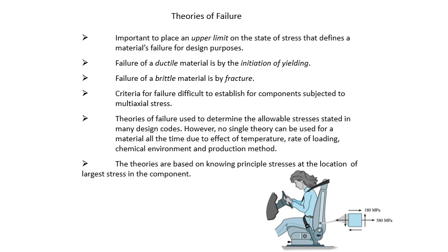Why do we need to know theories of failure? It is important for us to place an upper limit on the state of stress that defines the material's failure for design purposes. So normally we use this theory when we design a new product from scratch, or when we do design checking. It checks the upper limit or the maximum value of stress that can be applied to a component or object. And then we look at two different types of materials.